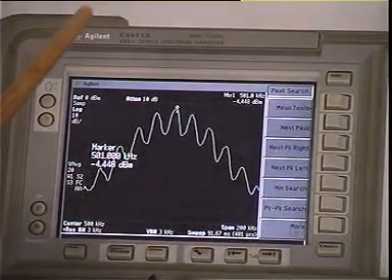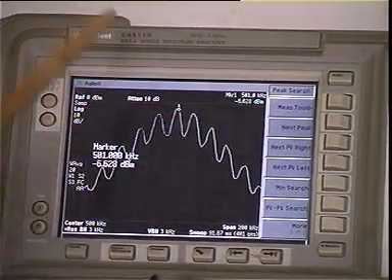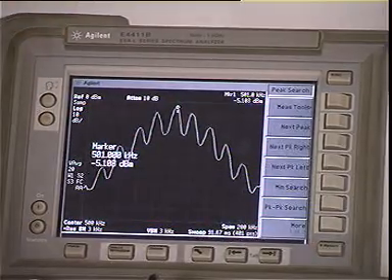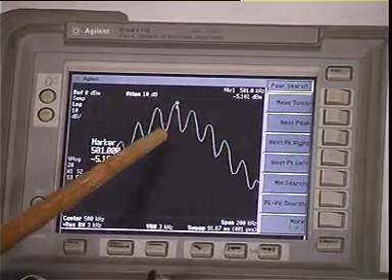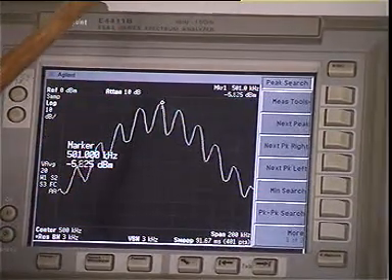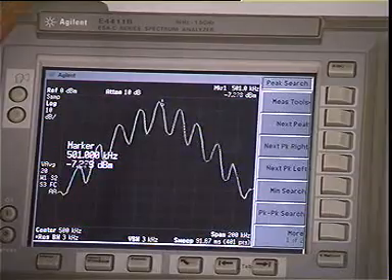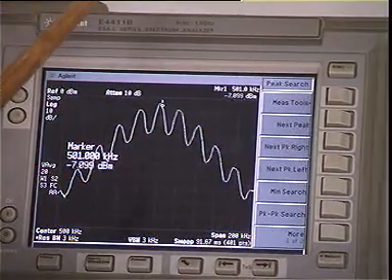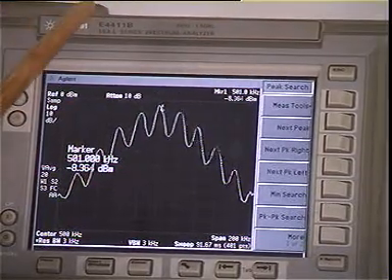There will be a particular value of the message signal amplitude where the carrier power would go to the first null. That is, the carrier power will go to 0. The position at which carrier power goes to 0, that's the first carrier null. One can find out the value of beta there. Beta at this value will be 2.4.